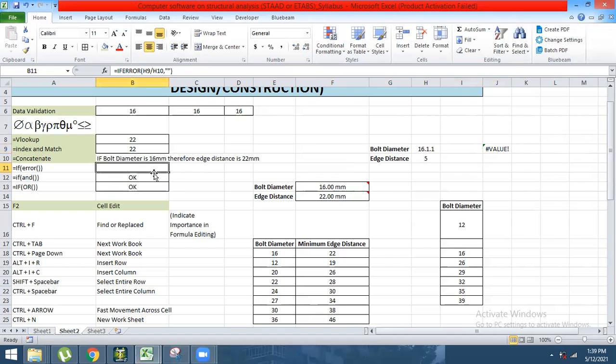Okay. Rather, if you put IF ERROR, it will just simply make it blank. Okay. So this is the syntax. IF ERROR, our value, then comma, then that's it, guys. Okay. Put a space, open and close apostrophe.